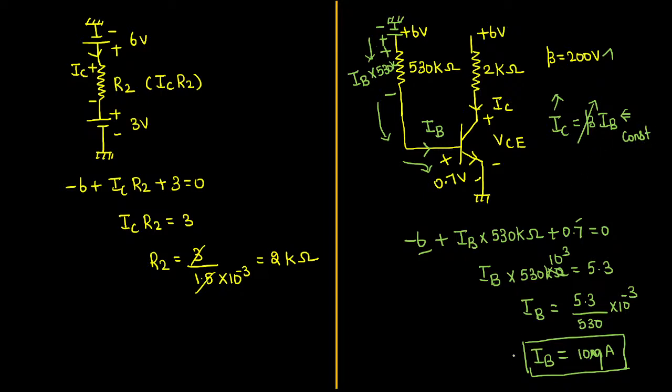The alternative I am telling is, now you found the value of base current. From this you can easily identify that the collector current IC equals beta times IB, whereas the value of beta is 200 and the base current is 10 microampere. So it will become 2000 microampere, or I can say 2 milliampere. Yes, that is correct, sir. This is what we found.